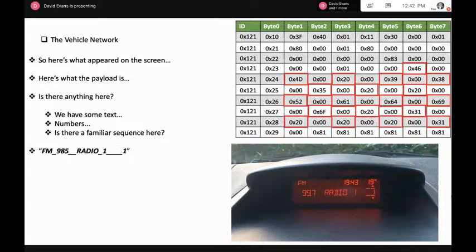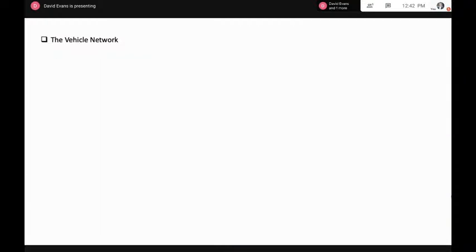And then I'm thinking to myself, they look very familiar. Are they ASCII characters? Yes, they are. You'll notice that in the top left-hand corner, we have the characters F and M, which are represented as hex 46 and hex 4D. Then it jumps down onto the following line and starts at hex 20, which is your ASCII space. And then it's pretty much just an entire string of 17 characters. That's what I just tried to show there. And that is pretty much it.